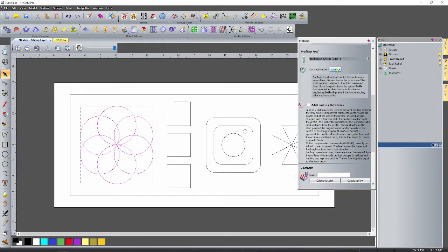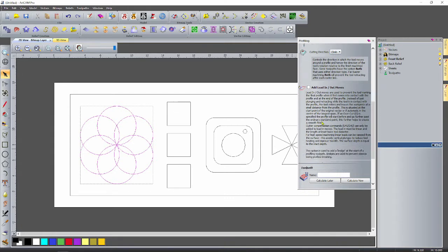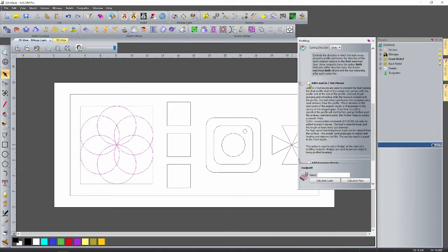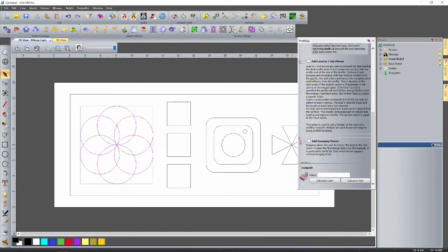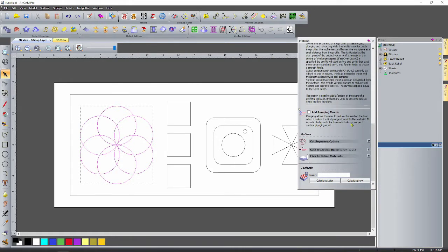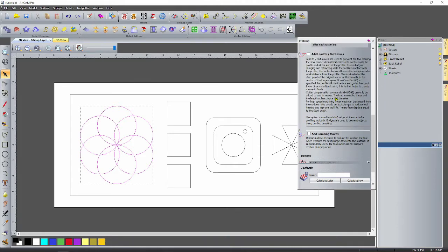And then we have two types of cutting, climb or conventional. There are many different YouTube videos talking about that, but I prefer climb for now. You can have fancy movement to go inside the material, ramping. Usually we use it for harder material or to have a better finish, but that's okay for me. I don't use it now because it's going to increase the processing time.